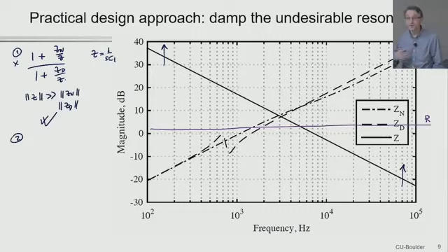If our impedance, instead of the capacitance, were just a resistance, the interaction here and here would be just fine because we would have 90 degrees of phase shift, or around 90 degrees of phase shift, and the impact on the correction factor and thereby on the overall transfer function would be very small. So that's great, but of course in the SEPIC converter, if you replace that capacitor with resistance, the converter not only doesn't work, but even if it does work, in some sense, you're going to be dissipating power on that resistor, so it doesn't make sense.